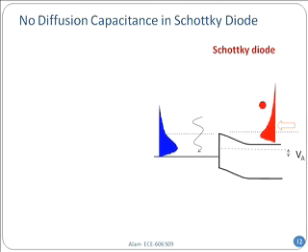And the reason it happens is because as soon as the electron comes in, when it's this much high in energy, it has no band gap or anything, right? In this region, phonons will immediately scatter it down, as if it has recombined with the majority carriers immediately. As a result, it is not sitting up there slowly responding and diffusing. As a result, you do not have any diffusion charge. And if you don't have any diffusion charge, as soon as the charge comes in here, then it responds with the dielectric relaxation because it's a majority carrier. And I do not really have to wait for the electrons to gradually go back and forth and respond with the minority carrier lifetime.